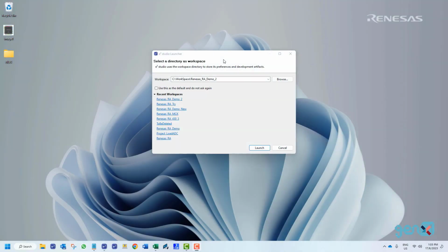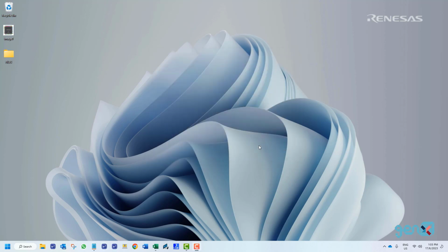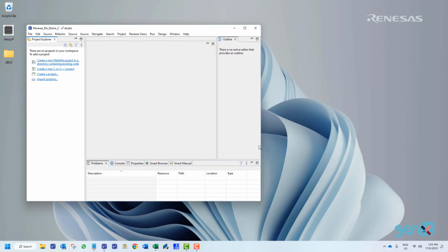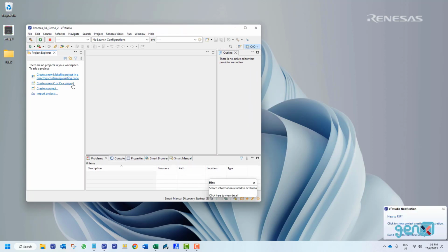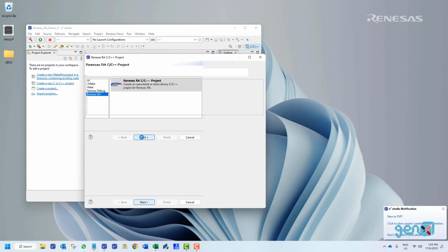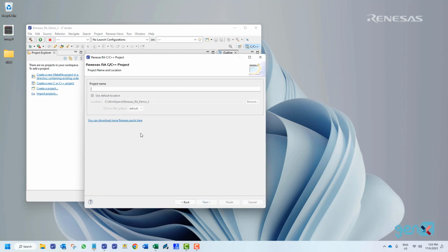In this video, we're going to look at reading temperature values from the integrated temperature sensor on the EK-RA6M4 board. As usual, we start by opening the e² studio and launching a new project in our workspace. We select a C/C++ project. Name it My ADC.